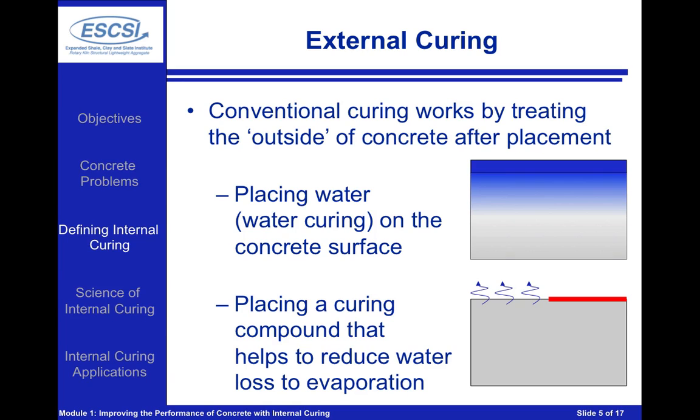It's also very important, when we think about the idea of water ponding on our system, that we recognize that as we move to higher and higher strength concretes, our concretes are becoming much more dense, much less permeable, and that really limits the depth to which that water can get into our concrete surface. And many times that properly cured layer may be limited to the outer inch or two of our concrete, with the core of our concrete not getting sufficient curing water.